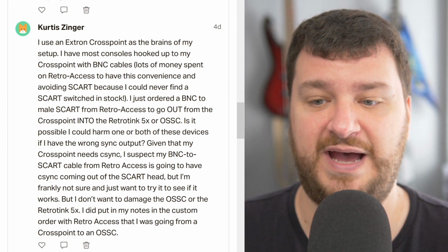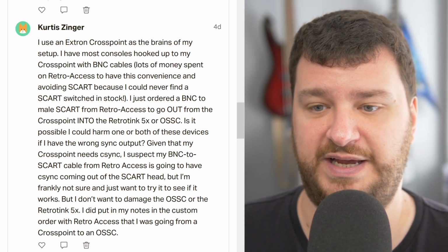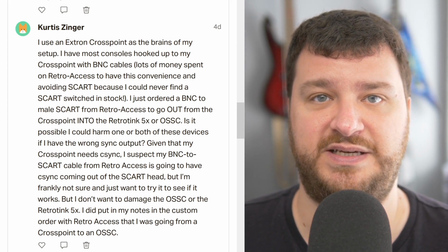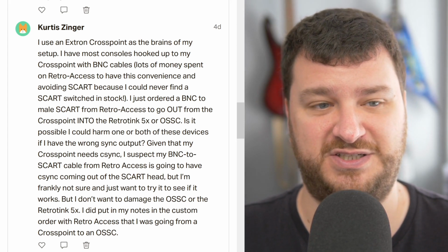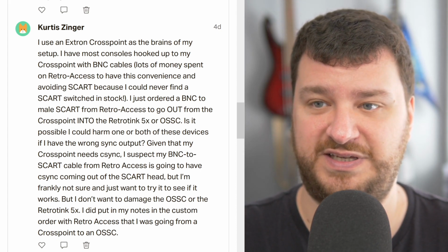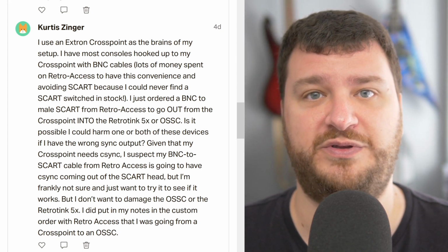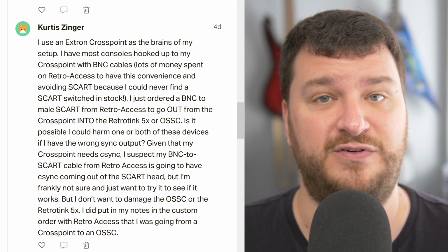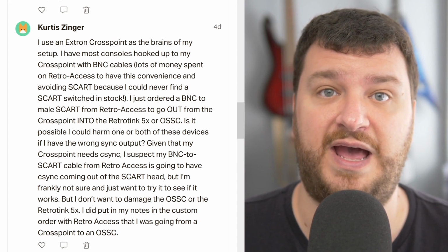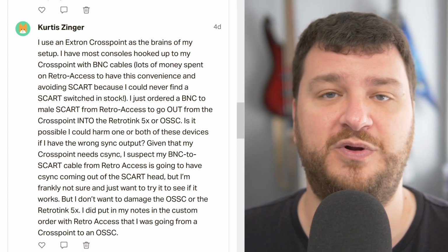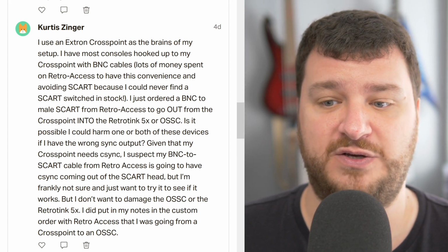anything that has a SCART input to it, you want to make sure that you feed it the lower voltage sync. So you would just need a BNC to SCART adapter that has that resistor in there somewhere. The easiest way to test is just touch the 2 points, the sync pin and pin 20, and then the signal line of the sync line with a multimeter, and see if it reads 470. If it just beeps as if there's no connection, like when you touch the probes together, that means there's nothing in there and you need to add one. But it's got to be one of the easiest mods you could do. Just a little bit of patience, put it right in the SCART head, whatever, and that's all you need.